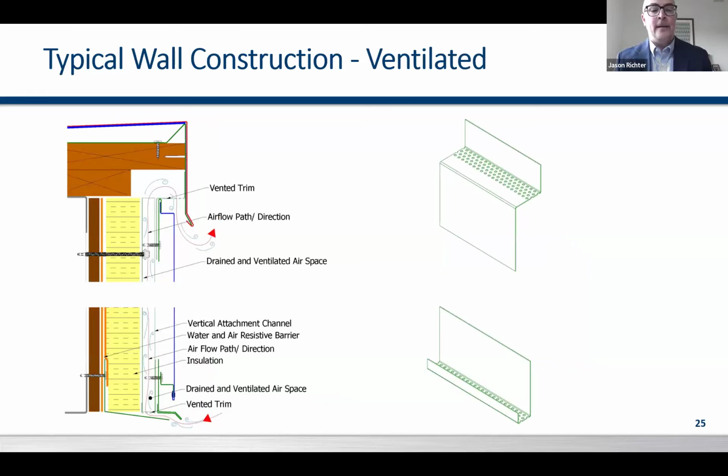Ventilated takes that concept and adds to it by allowing the moisture to vent out at the top. So you are allowing the liquid moisture to weep out at the bottom, but with a rain screen made out of metal specifically, that airspace gets very hot very quickly. So think a summer shower moves through, and then you have the sun come out and that moisture is in there and getting heated up very rapidly.